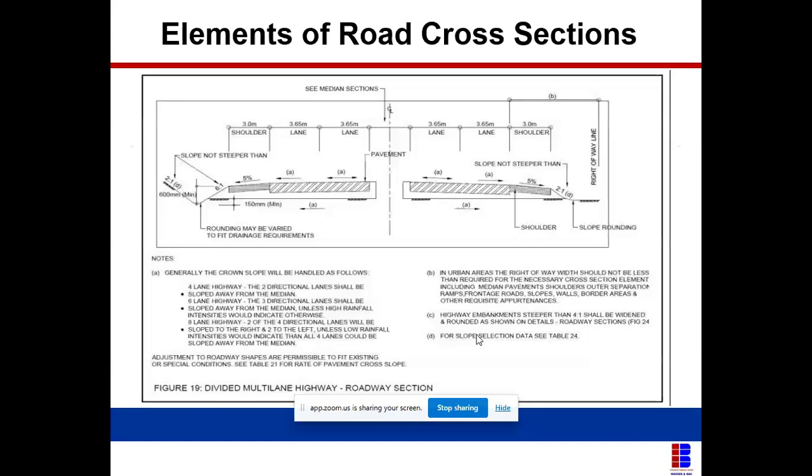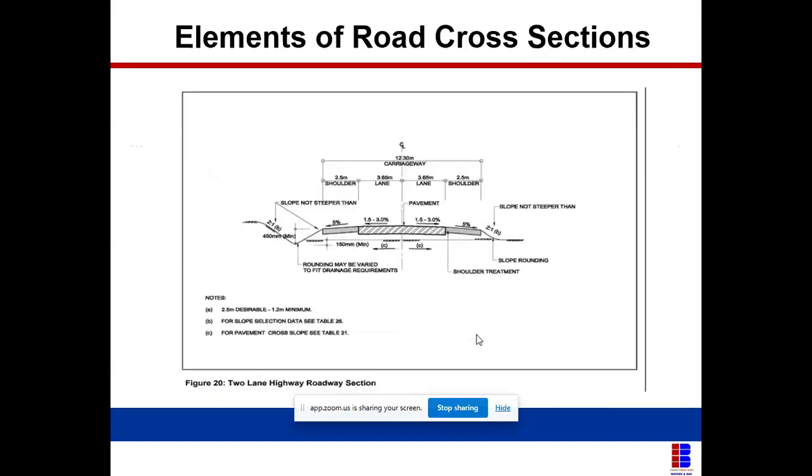So that was the typical cross section of the road, showing your verge and all. These are the typical cross sections of the road. Now you can see showing your carriageway, 3.65, 2.5 shoulder, no steeper than this and all. So desirable for slope section. So you can see the camber. This is showing 3% here now. 3% there. For the shoulders, the cambers are normally 5%.